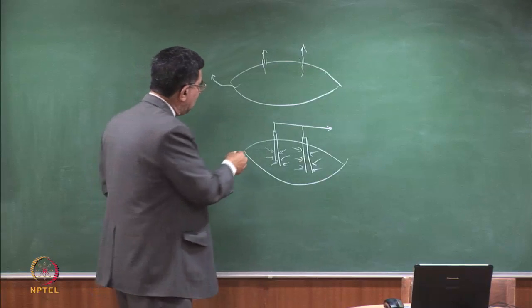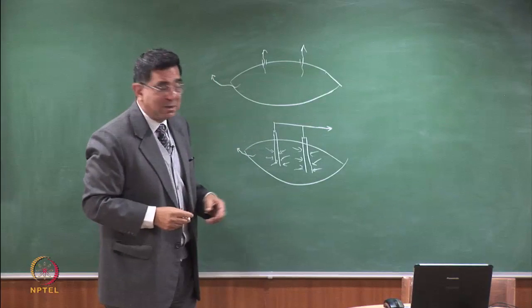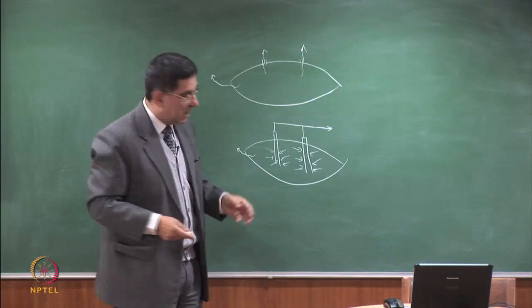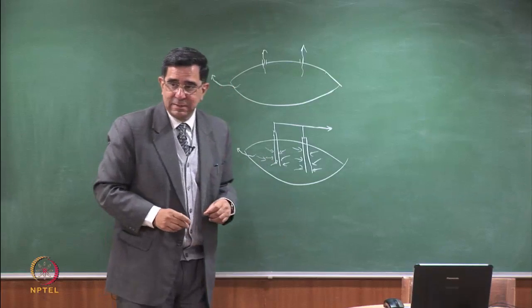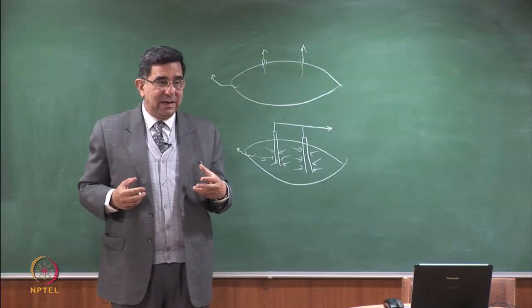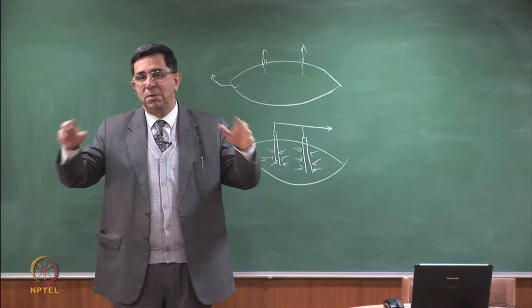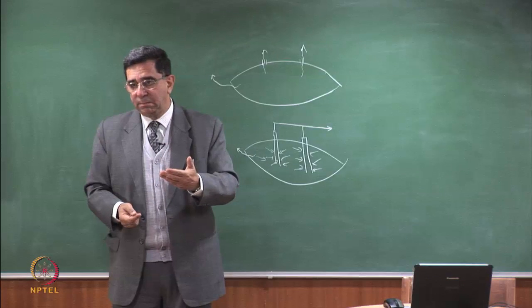What happens to this gas which was escaping? Since there is no positive pressure in the heart of the landfill, maybe this doesn't want to go out, it wants to go this way. So when you do active collection, your efficiencies go up. When you put geomembranes and containment at the top and the bottom, your efficiencies go up.